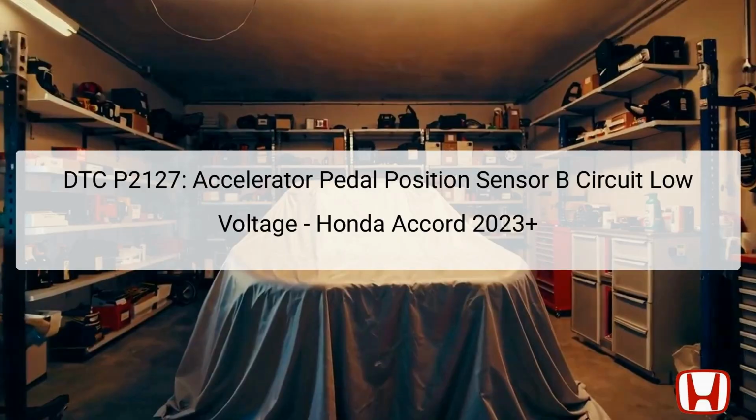The Diagnostic Trouble Code DTC P2127 pertains to the Accelerator Pedal Position (APP) Sensor B, specifically indicating a low voltage condition in the throttle position (TP) Sensor E circuit. This code is significant as it detects an abnormal output voltage from the APP sensor, which informs the Powertrain Control Module, PCM, about the driver's acceleration input.